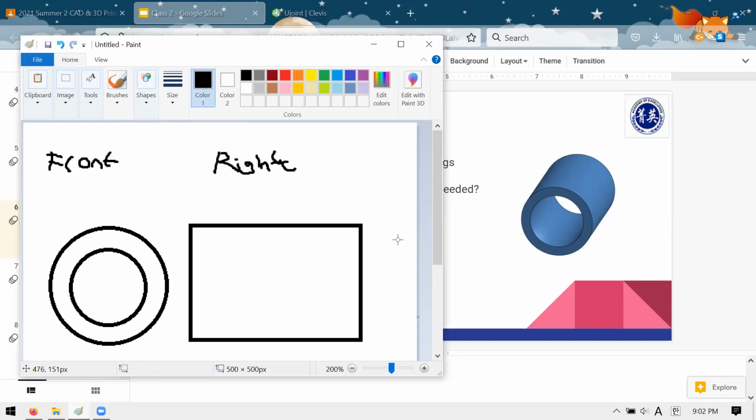And as we talked about, when you look at the side of a 3D object with internal features like a hole, there's some information that you can't see with your eyes, but is still present in the geometry. And that is that hole. If I just showed you this rectangle and you didn't know about the front view, you just knew about the right view, there's nothing to stop you from thinking that it's a completely filled-in solid cylinder.